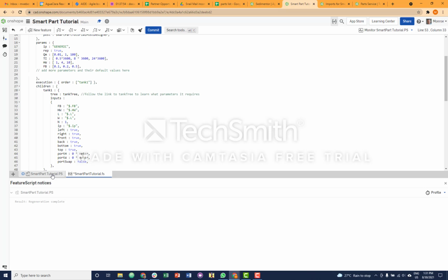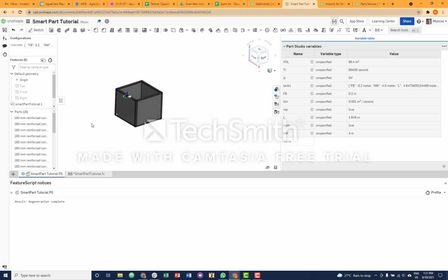We have this one tank placed on the origin, and we want to place a second tank, and this second tank, we would like it to be 10 meters away, and we also need to have some elevation difference so that water will actually flow from the one tank to the other. So let's make the second tank be a whole 4 meters lower than the first tank.